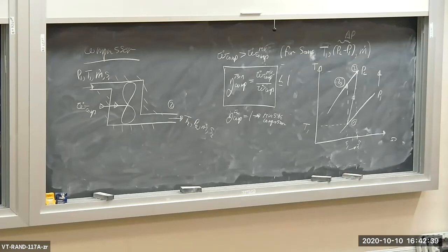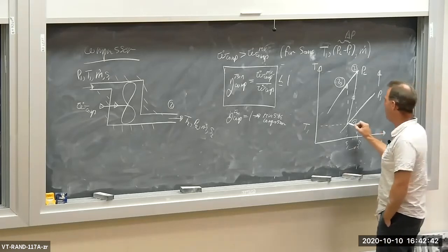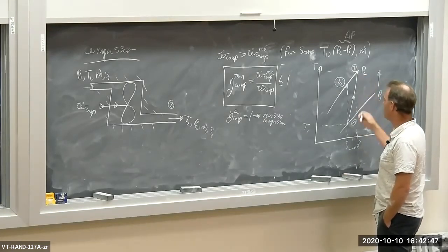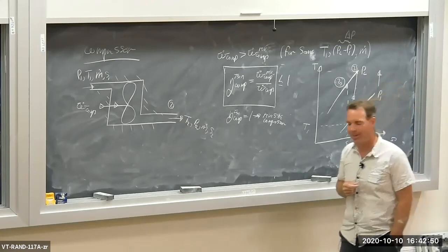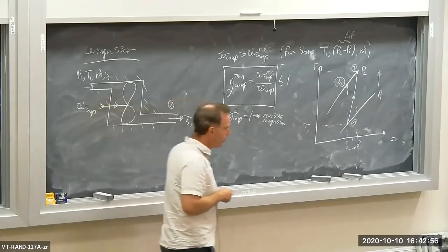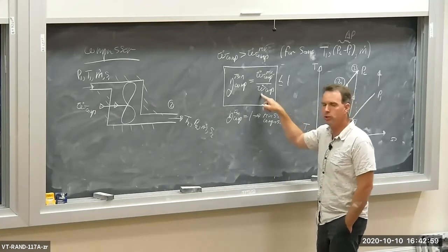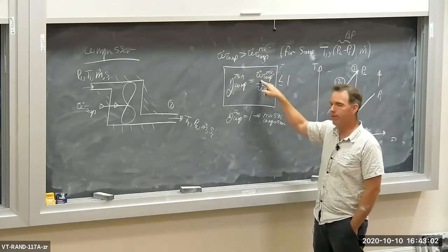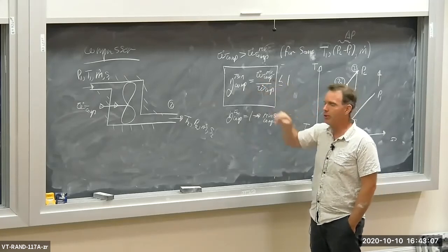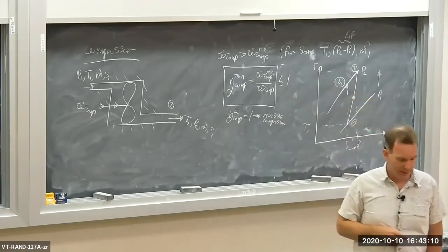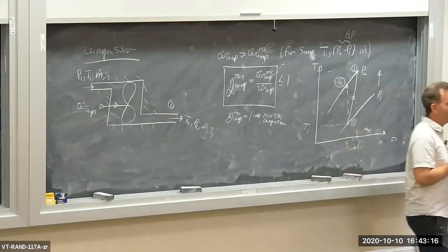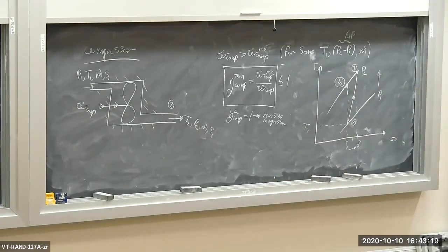Delta S from 1 to 2 is going to be positive, and it follows a path which is not vertical, but at some angle from state 1 to state 2, with a resulting increase in entropy from the inlet to the outlet because there's some entropy generation inside. The real device consumes the most power to pressurize the flow. The reversible device consumes the least power. So we take the ratio of the two and we call it the isentropic efficiency. If your isentropic efficiency for some device is 1, it necessarily means that the device is a reversible compressor, okay?